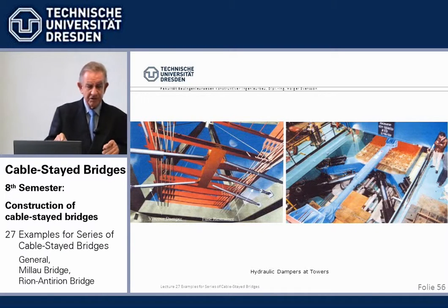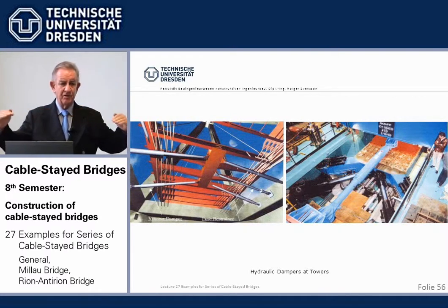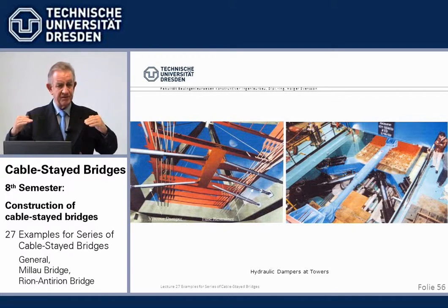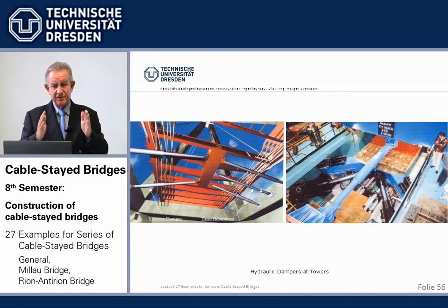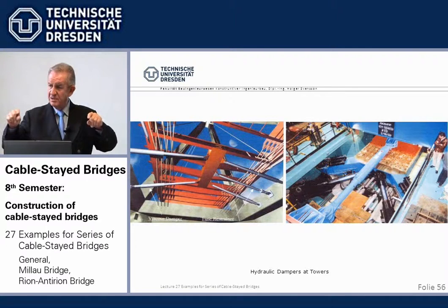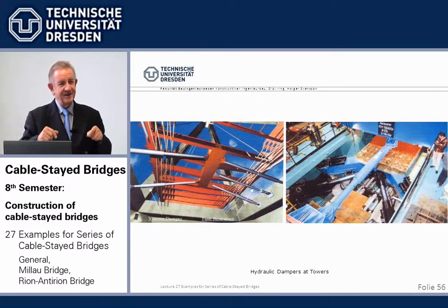Now, I've told you how we stabilize the tower head. How do we cater for the beam changes in length? We do that by having the beam over the full length of something like 2.5 kilometers freely in the cables. There is no longitudinal connection between the beam and the towers. It's just like a swing, and it can swing like a children's swing in a play yard.